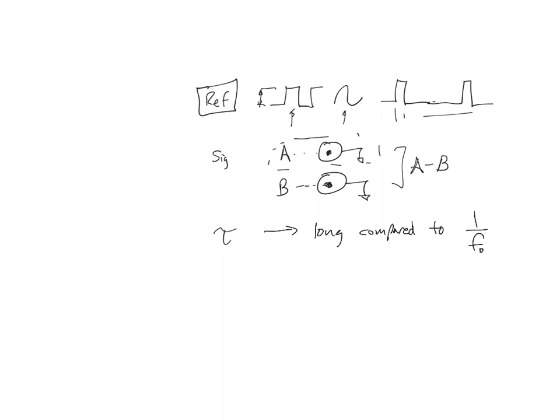And then finally, you're going to set the phase, the reference phase. You're going to phase up the reference with the signal. You're going to do that by first zeroing it. Zero the output, and then switch the phase by plus 90 or minus 90, whichever you prefer. That'll just send the output to either very negative or very positive. Okay. All right.